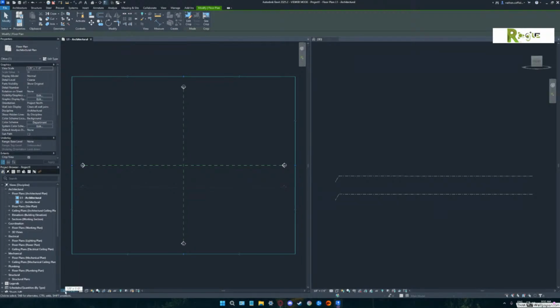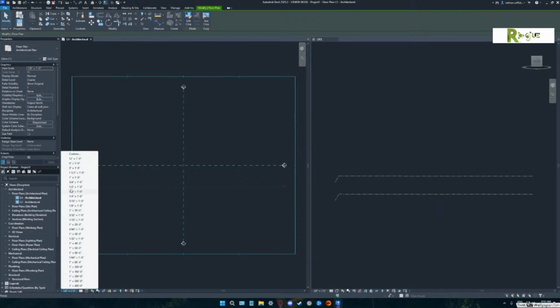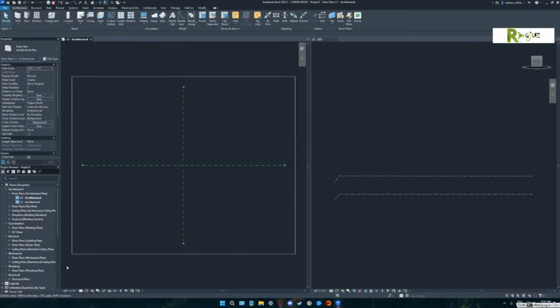Down here. Go ahead and change that to anything else. I don't care. You should see all the section heads got a little bit smaller. Every piece of text would have gotten smaller. Every drafting element. That's what the scale does for us. It also changes line weights and other things. But notice how you changed it to 3/8 down in the bottom.